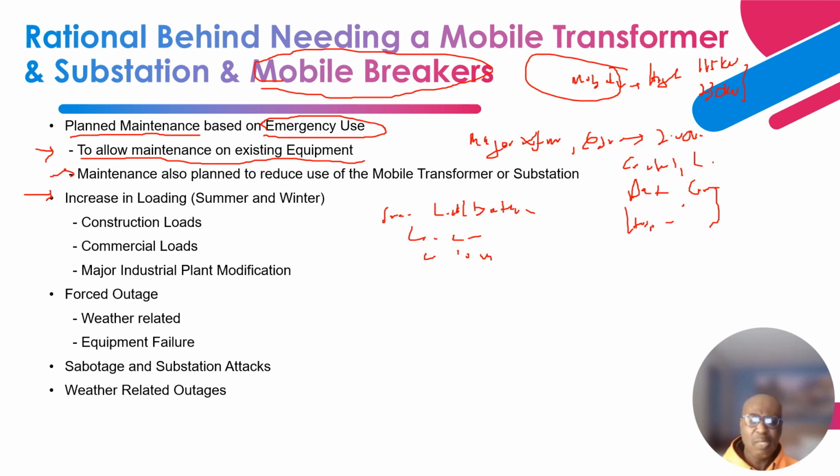That itself is all part of the increasing load, so you have to account for that. And to make it worse, during summer all those air conditioning motors consume a lot, especially the starting current and the starting reactive power. Basically, that can cause a sag in the voltage and can cause power quality problems. So there's the need to account for that.